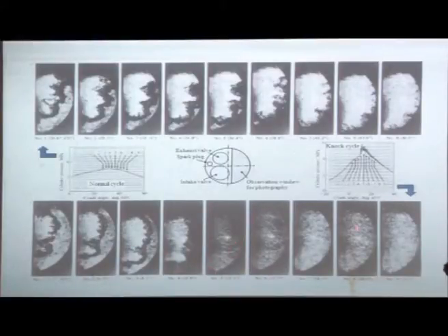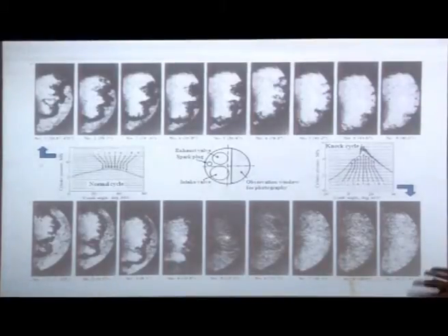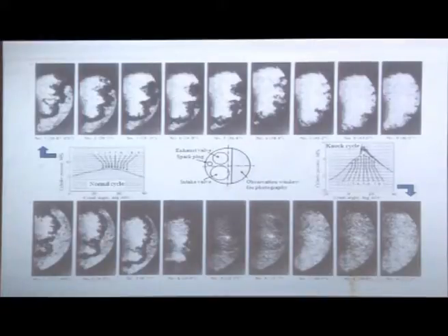Everything becomes very unique. And what you see here is basically, here there is a pressure wave which is moving in this direction. Here once this is consumed, this moves in the opposite direction. And then it leads to amplitudes being different, rate of heat release is different, rate of pressure rise is very different. And what is loose in the combustion chamber? Only the piston.